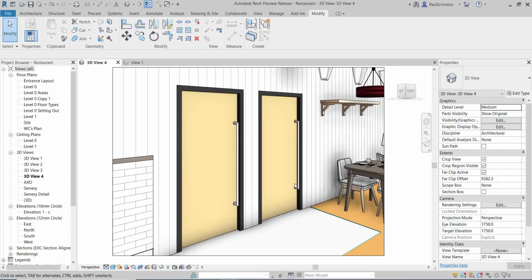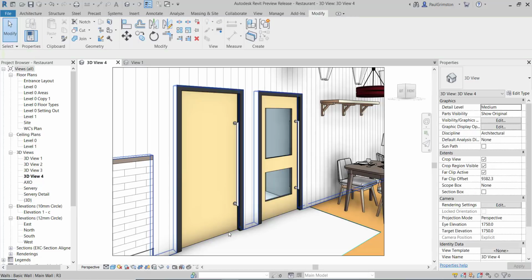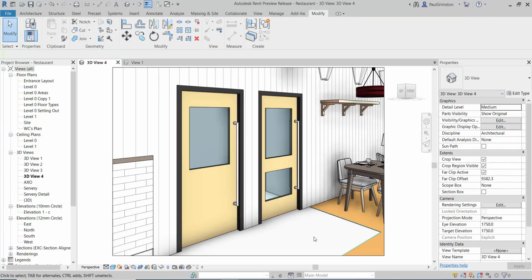So back in our project with the door family, where they're all set up and working now, we've got the two doors here. They're both the same family. We've got these set up as instance parameters here, and we just have some checkboxes so that we can tick that we've got the vision panels as we need them. This way, we can use the same door family, but specify whether it has vision panels by instance.